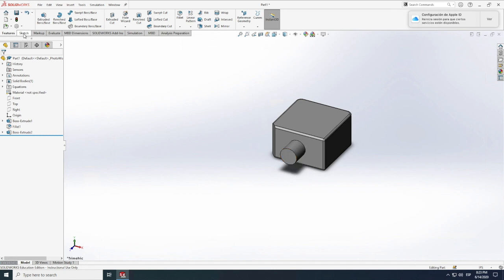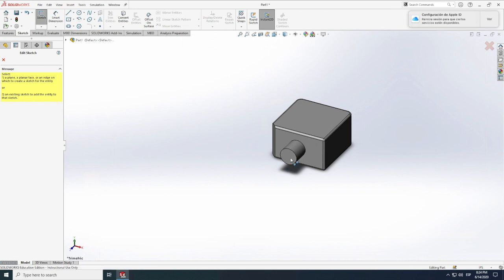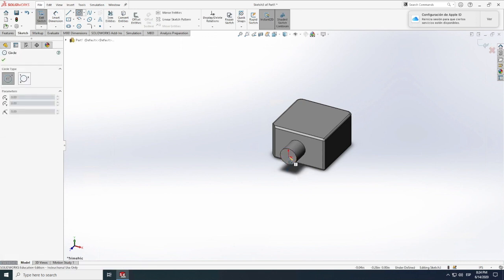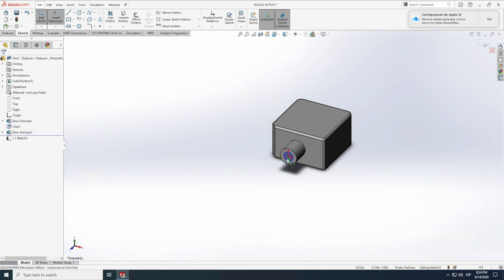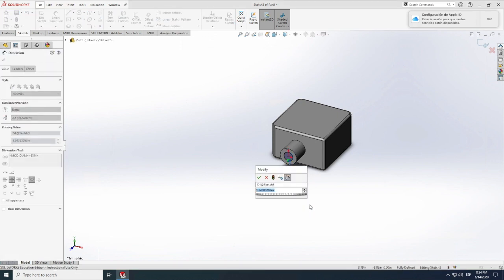Now let's go back to sketch. Let's go here to sketch. Let's click on that surface in there. Let's do another circle. Again, that point will be this time the center of that thing. So again, I just clicked on sketch, then on that surface there, and then this set of axes appears there. So that's the point I'm choosing. Let's define that to be, I don't know, 1.5 inches diameter.